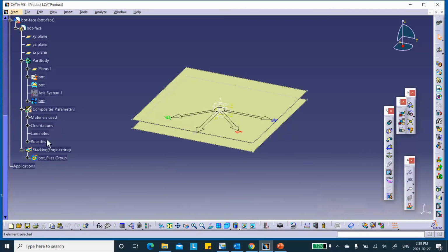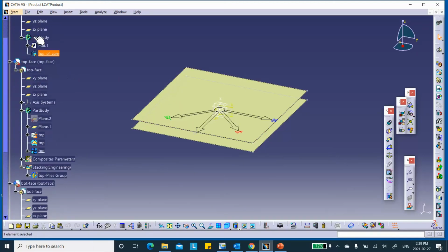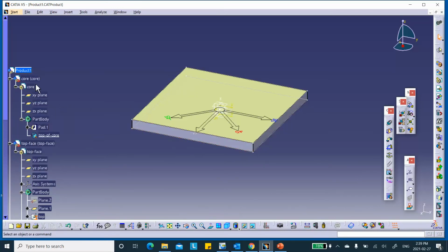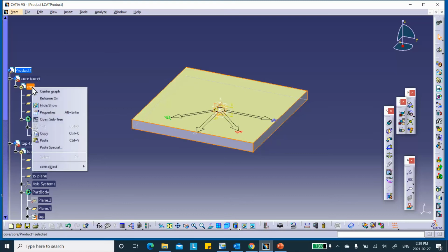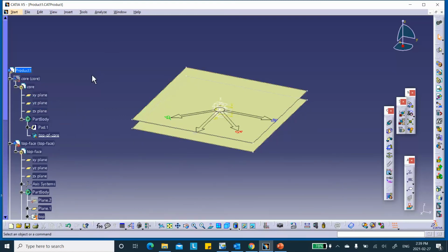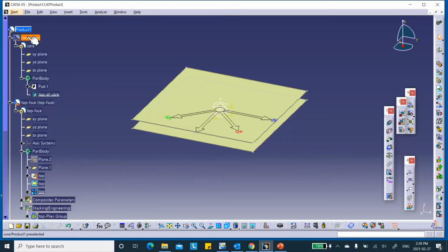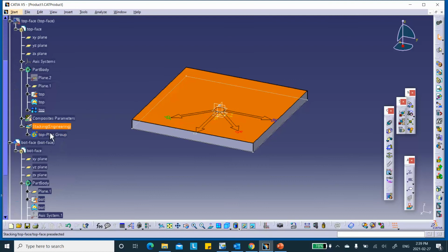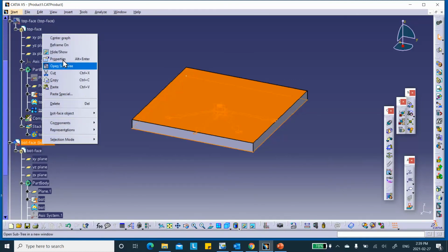All right, good. Now, as far as the model is concerned, we are done. Your core is also there. If you say show it to me, it'll show it to you right there. But let's do the meshing first. So I'm going to uncheck this or hide the core. Okay. Actually, I'm going to show the core, hide the top and the bottom surface, hide and hide.